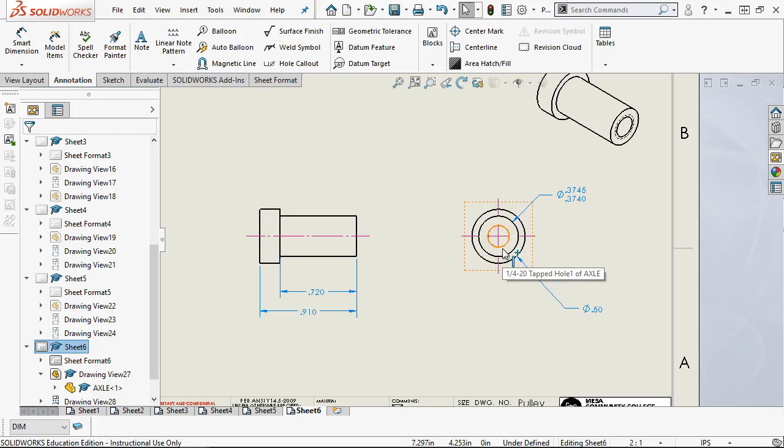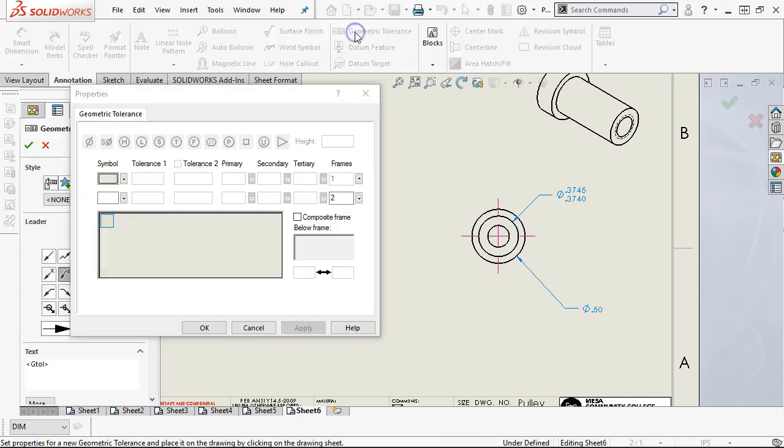It's not that critical. I just need to take a step back and look at it and go, really, I need this to be cylindrical, so when it comes up and it butts against the faces of the plates, this surface needs to be perpendicular to the center line. But other than that, I really don't need anything else. All right, so let's go ahead and apply a cylindricity.